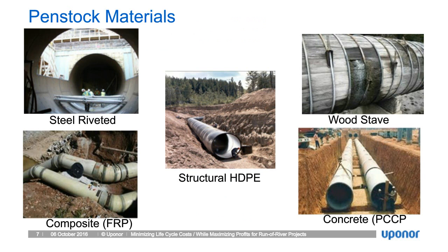Just a quick overview of the penstock materials, steel riveted. A lot of this was installed back in the 1940s and more so associated with dam applications where you have higher head pressures, which the tensile strength of this steel can more than accommodate. Of course, steel way back then was inexpensive, not so much today, so that's part of the drivers for the development of new materials.